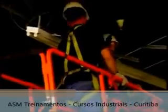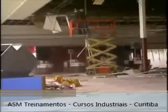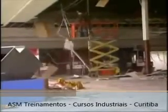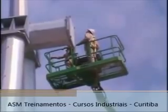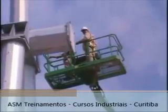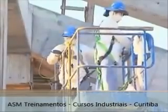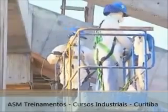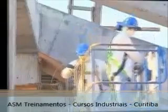Never tie off to an adjacent pole, structure, or piece of equipment while working from a lift. Personnel should always stand firmly on the floor of the lift. Never sit or climb on the basket or guardrails, or use planks, ladders, or other items to attain a higher work position. If additional height is needed, then the lift should be extended, or if necessary, a different lift used that is appropriate for the job.